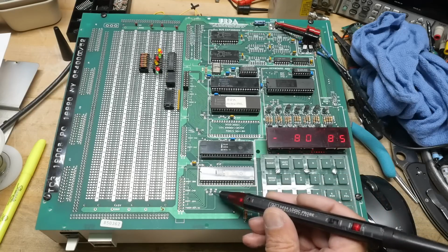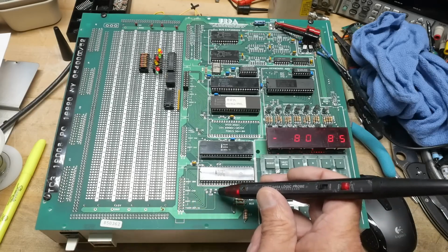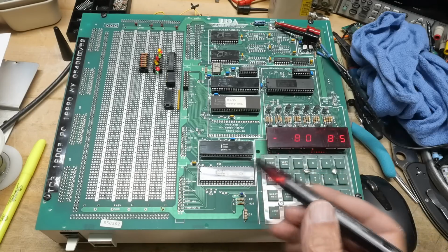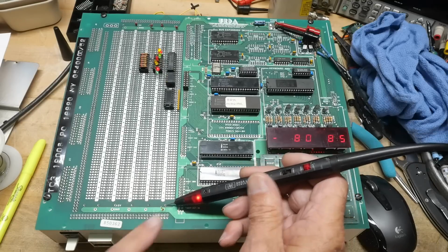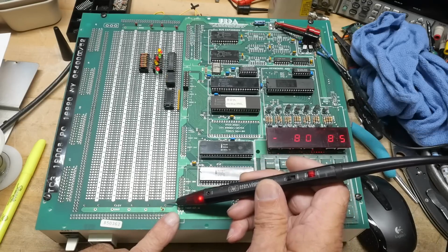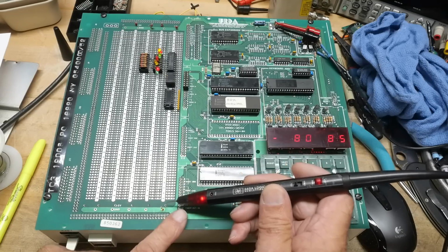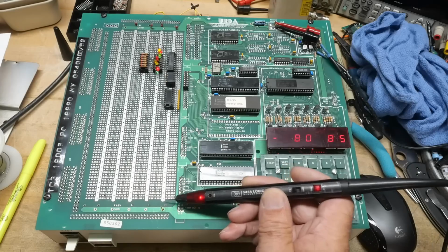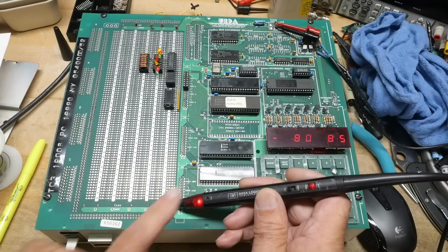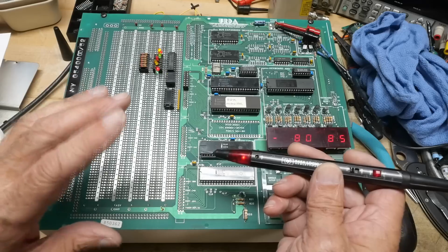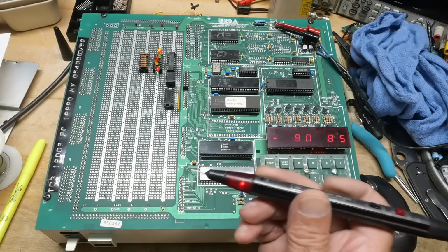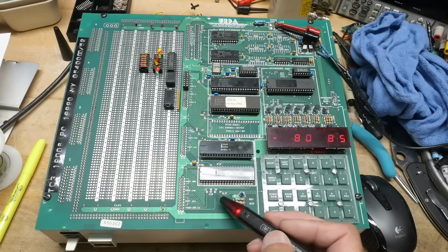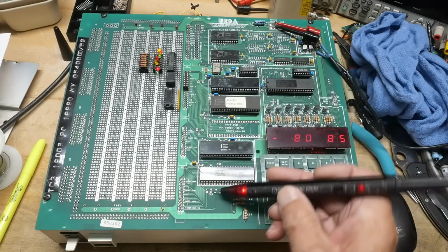And so that means that there is something changing. It goes high, low, high, low, high, low. If I go to something that's just high, you can see that the little light bulb gets brighter. That's a high state. And if I put it on ground, it goes to a low state. So when it's off, it's low. When it's high, it's lit. And then in between, it's half lit. Okay, that's called a tri-state condition, when it's not connected to anything. So you can see something low, something high, or something changing, okay?